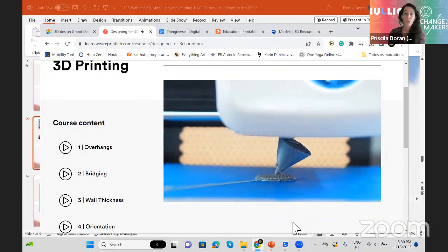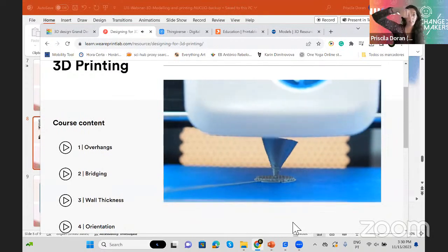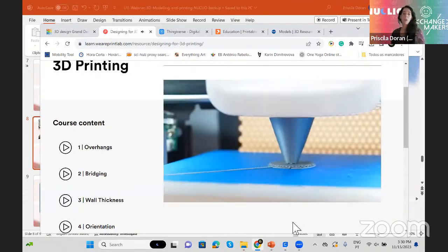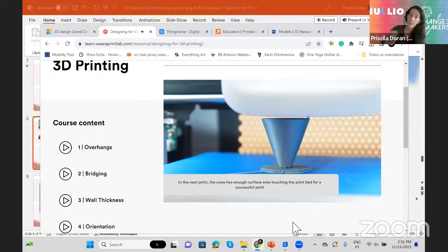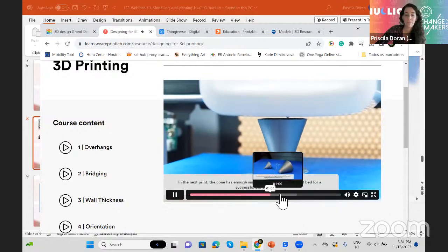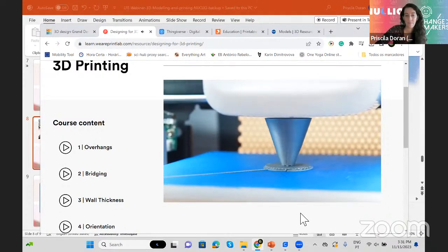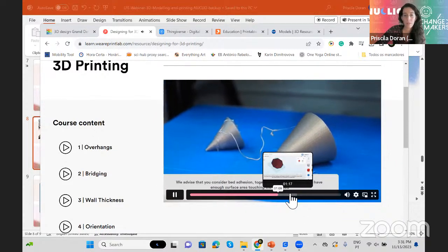So again, one of the options will be to turn it upside down, right? To start printing the big part and then the small. Or as they show it, if you can, make it less pointy on the bottom. It isn't wobbly at all this way.